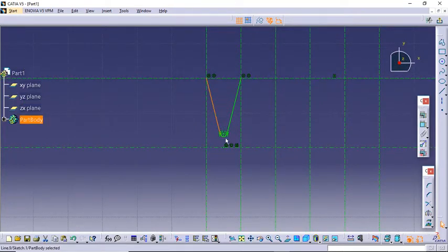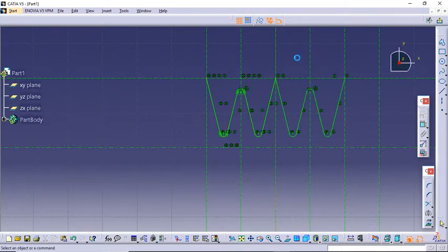Now what I can do is click on it and take the mirror image with respect to this line. So here I got another groove. Again smooth the sharp edges, because they may cut the belts of course, so we do not want it. Now again we will take a mirror image: hold control and click all the lines, click on mirror, click here.